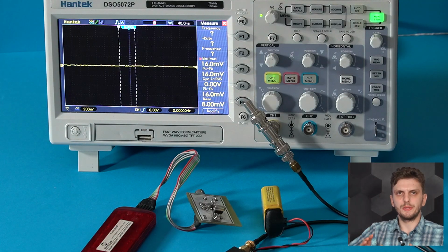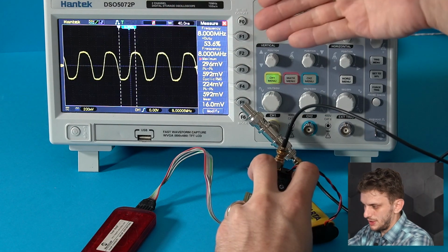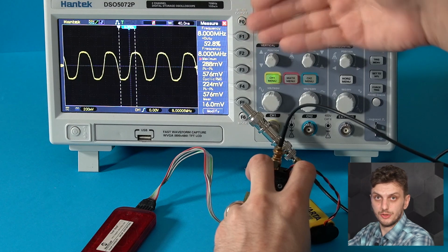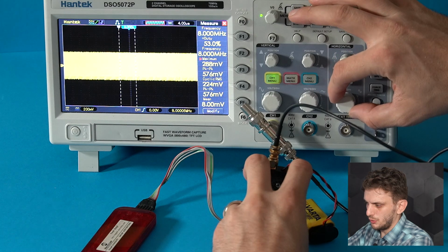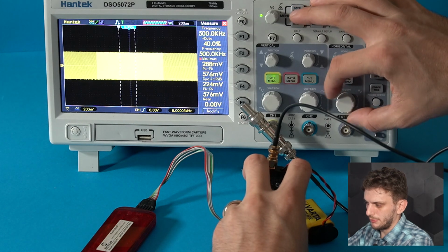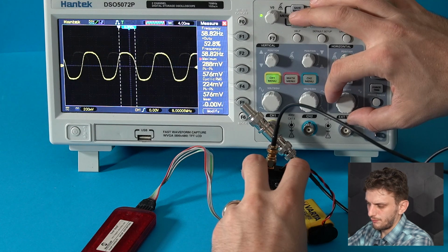And now, knowing that the probe works and that we have a good measurement without too much of an impact on the circuit, we can finally perform our startup measurement. Now, before performing the measurement, we need to do some settings with the oscilloscope. So with a time base of 40 nanoseconds, we see our 8 MHz clock signal, so everything is fine. But to perform the startup measurement, we need to work at a completely different time base. So something in the order of milliseconds.